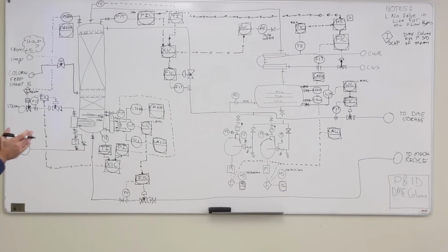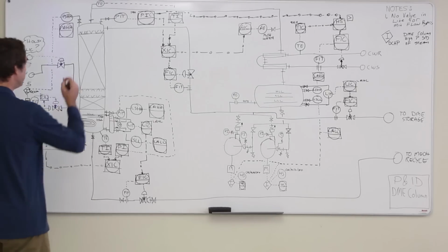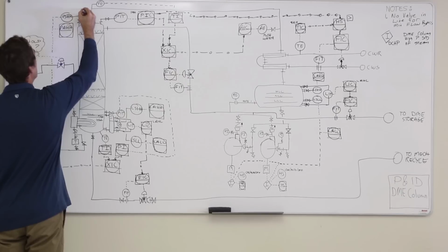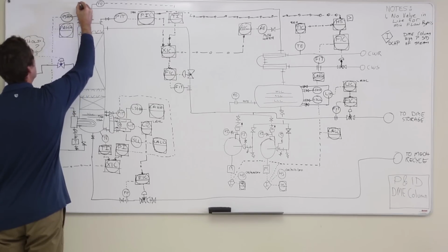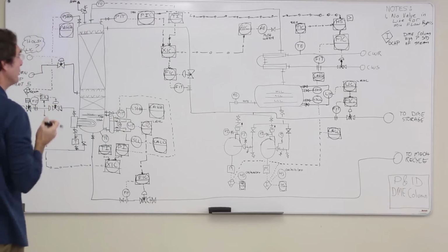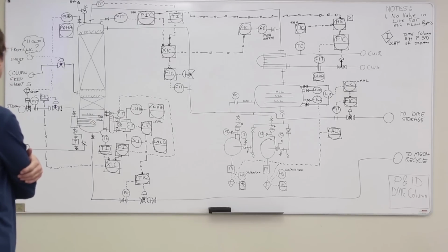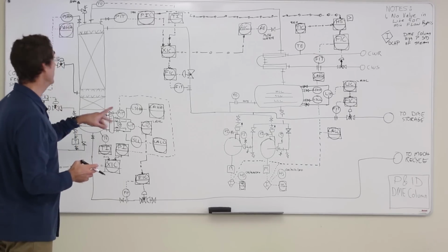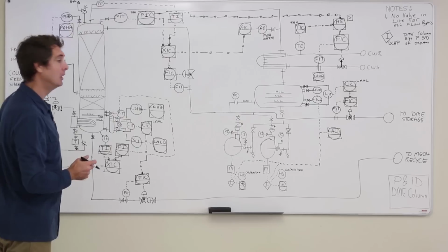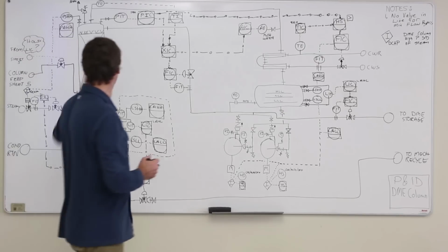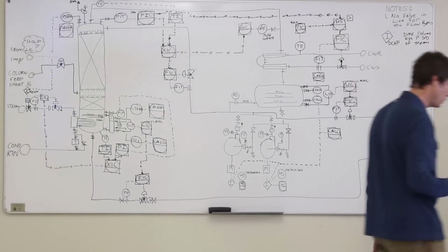interlock on high pressure to stop the column from overpressuring. And if that doesn't work, or there's another failure, then we need a relief valve. And I'm going to blow the relief to atmosphere because I think it's a pretty tall tower, and it's small. And I'm just going to deal with the environmental issues of that. Because I'm putting enough controls in, I'm going to make sure that relief valve never blows. And so I've got one interlock there, another interlock there. Did I think of any others?